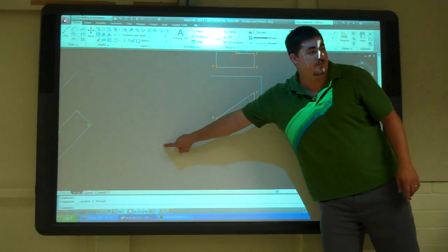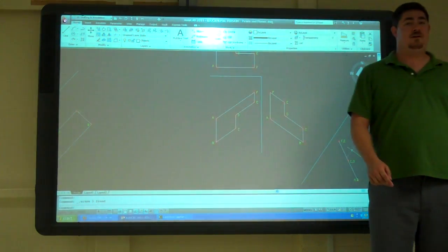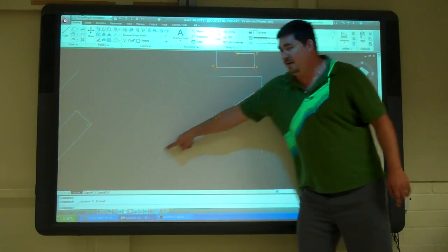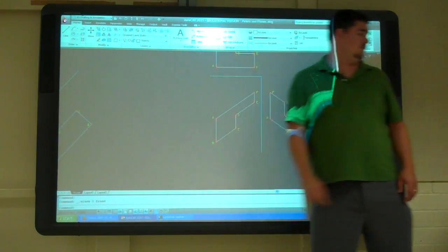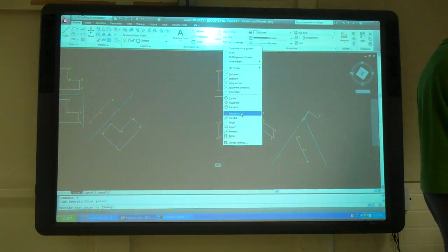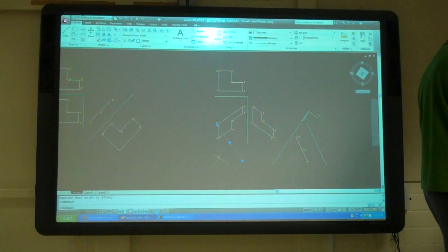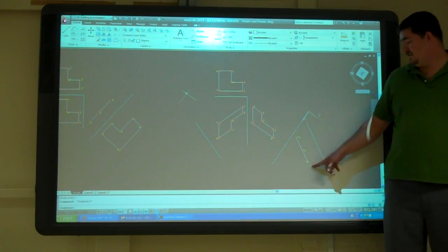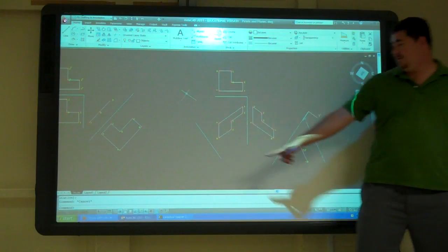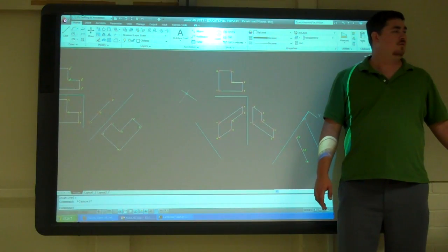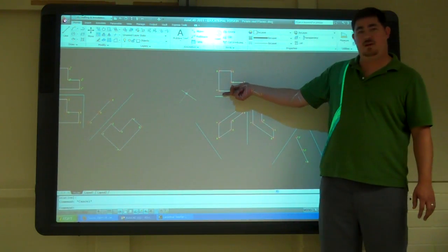So if I came this way up from this view, it would give me the same thing, because AF is parallel here. So if I did a folding plane there, would that give me the same thing as this edge view? Would this one give me an edge view? Yeah, right? Because A and F is parallel to the folding line here.